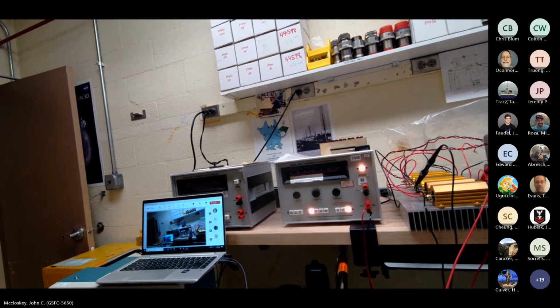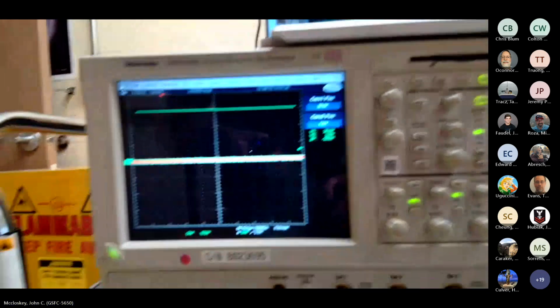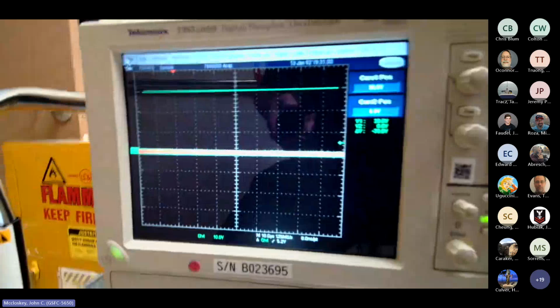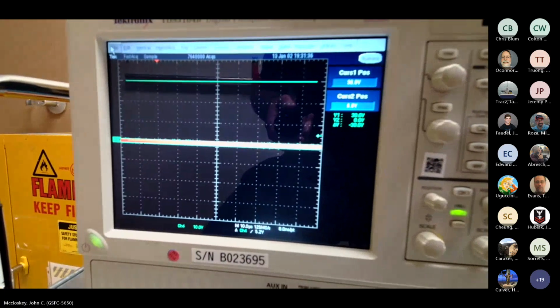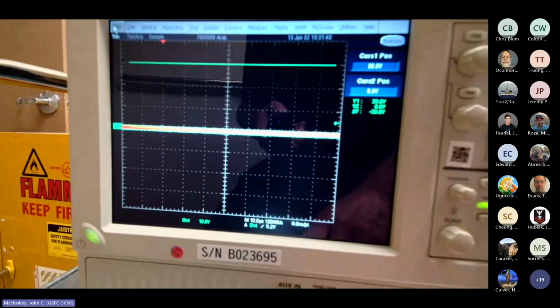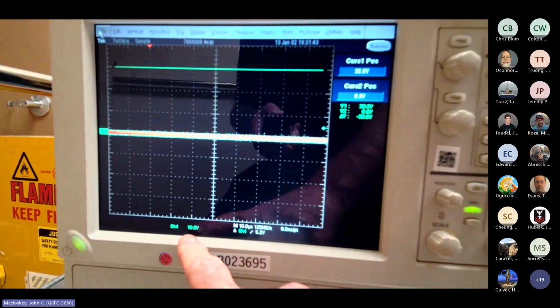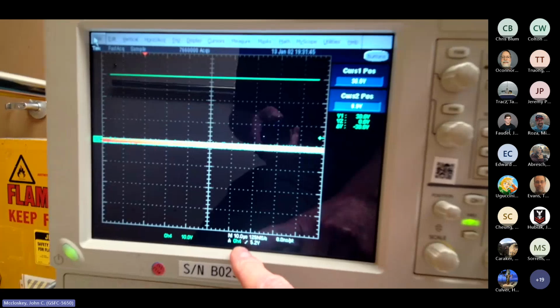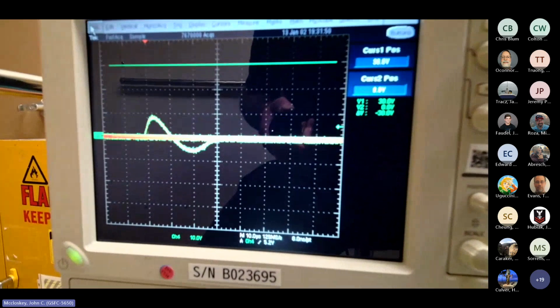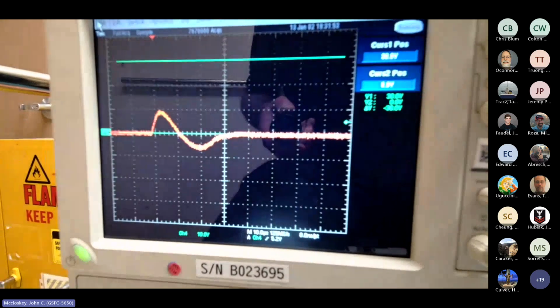All right. So I'm going to take this off of the stand and go over here. So can you see the scope? I have to readjust myself here so I can point at the scope and reach the generator. All right. So can everyone see the scope? Yeah, we do. All right. So it may well be rather blurry here, but we're at 10 volts per division and 10 microseconds per horizontal division. So I'm going to start to bring up the amplitude, and it comes up pretty quickly.